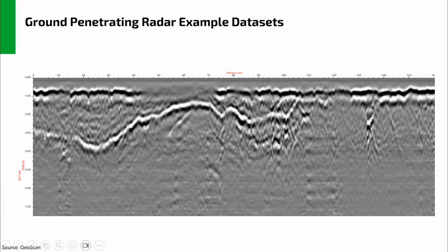Now, those are the interfaces where the relative permittivity or dielectric constant suddenly changes, either increases or decreases, depending on the material. Sometimes we can even tell which direction it goes. Actually, it's fairly simple, but it's not obvious most of the time. In complex cross-sections with complex reflection patterns, it gets really, really difficult. But this example shows one of the nicest cases, and that's what I was hoping to show you.